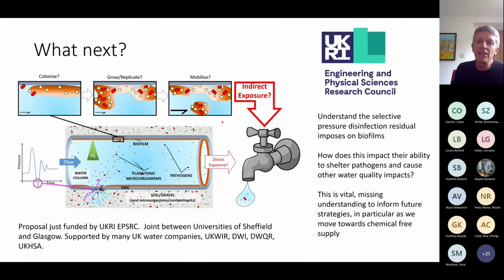But really trying to get to biofilms and this missing link between protecting water quality and our aging infrastructure, and therefore what should our disinfection strategies be going forward. Not necessarily saying we shouldn't chlorinate, although some countries do go for that strategy, but more what is the right chlorination strategy to give us the benefit in the bulk water and minimise the risks from biofilms or disinfection byproduct formation.